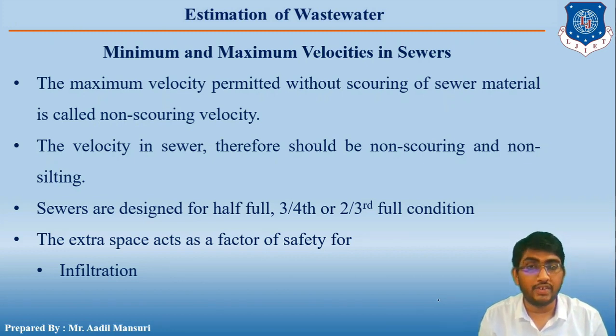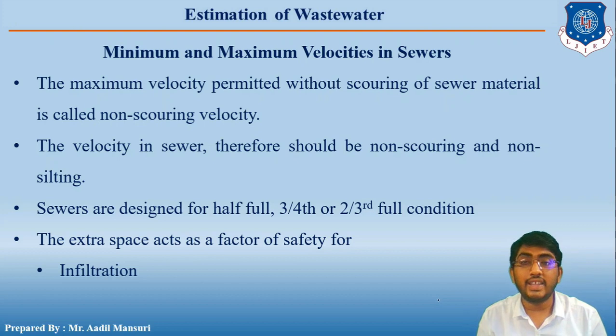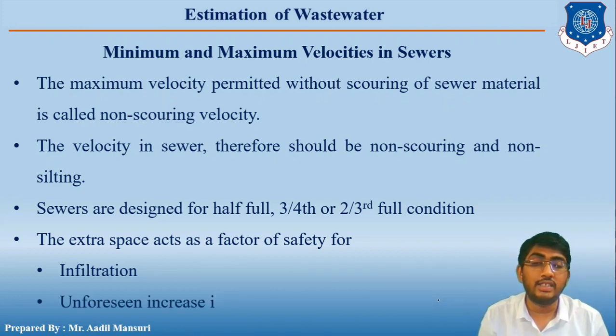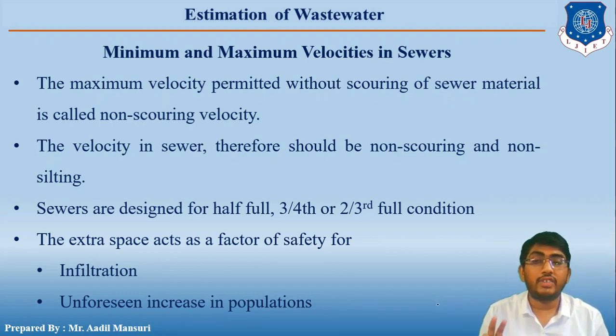The second is the unforeseen increase in population, that is, the unpredicted increase in population. So these are the two conditions we consider, and we design the flow as half full, 3/4 or 2/3 of the full condition.